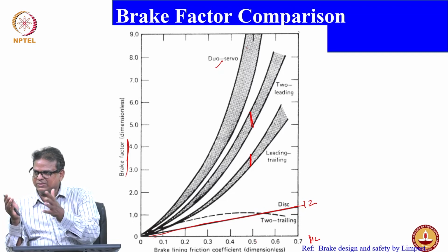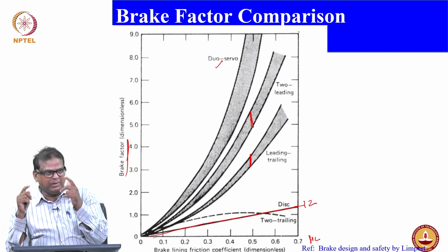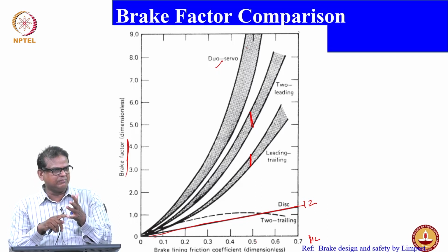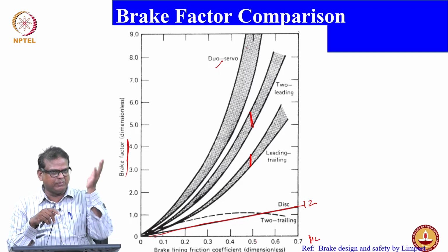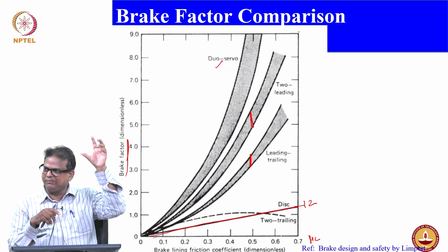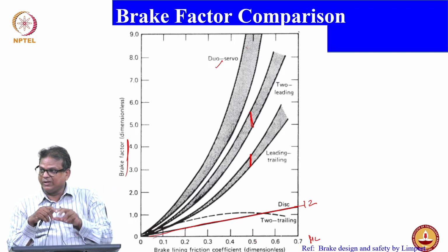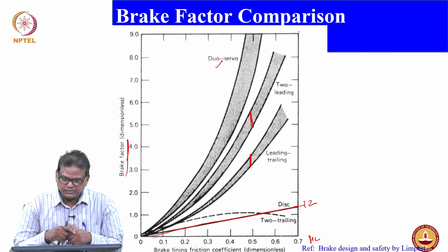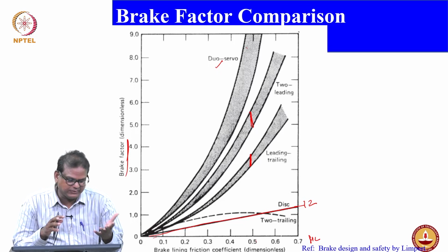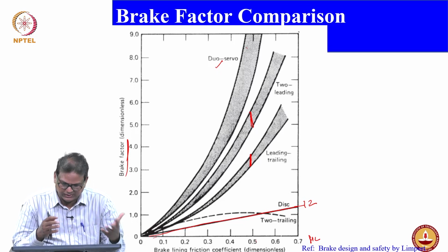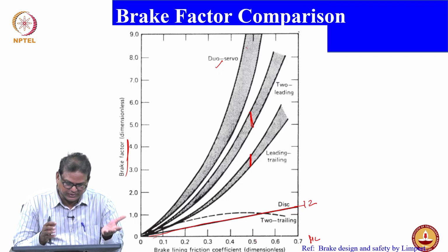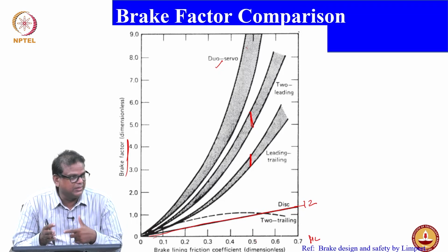No, right, there is no self locking, okay. But you have self locking in a drum brake system when Mn equals Mf. Remember the equation we initially derived. So you will have self locking, which is not advisable, okay. The question is, the brake factor is good for leading and trailing, whereas a disc brake will have a lesser brake factor, but has no self locking.